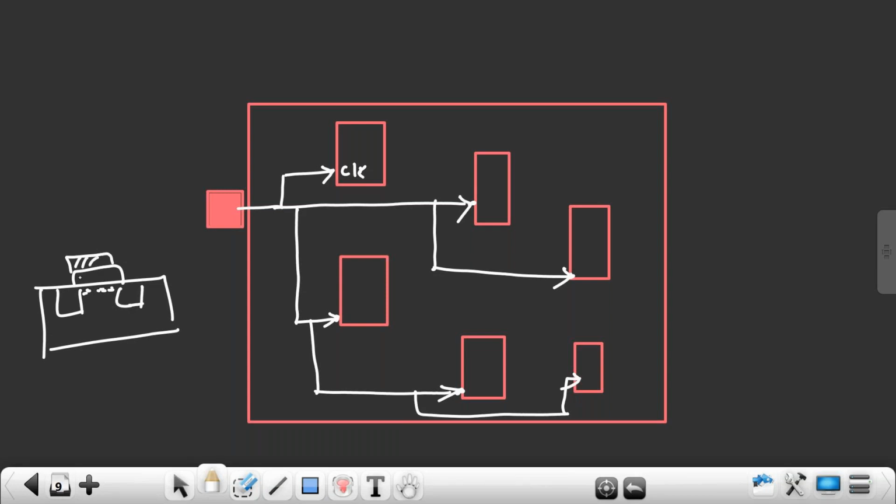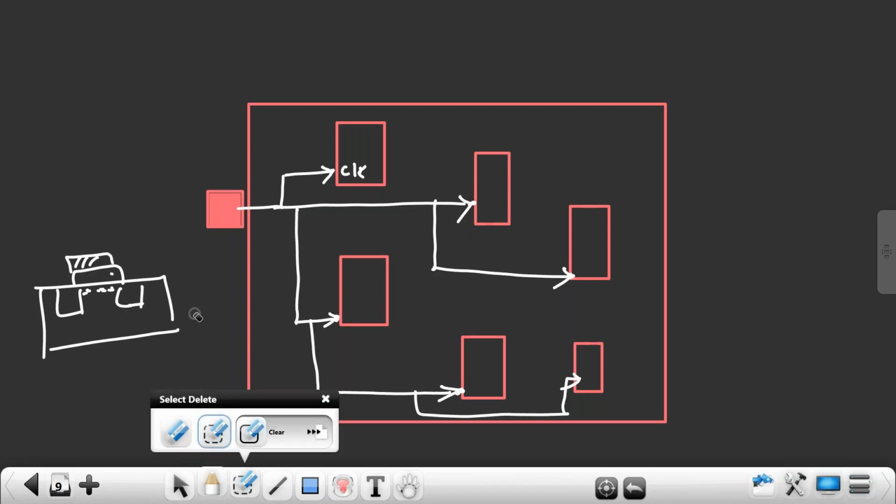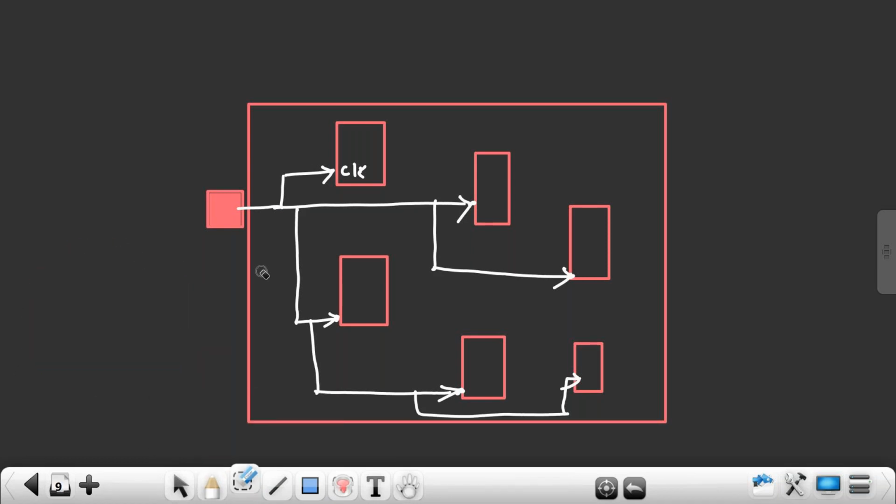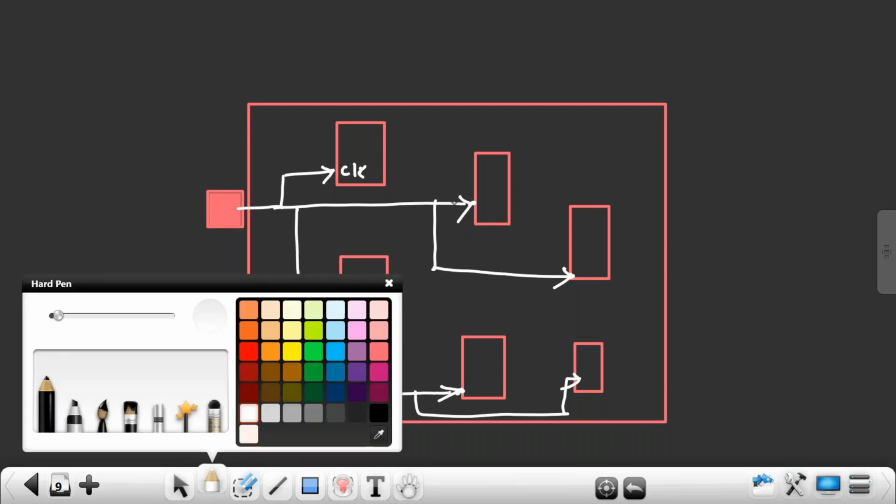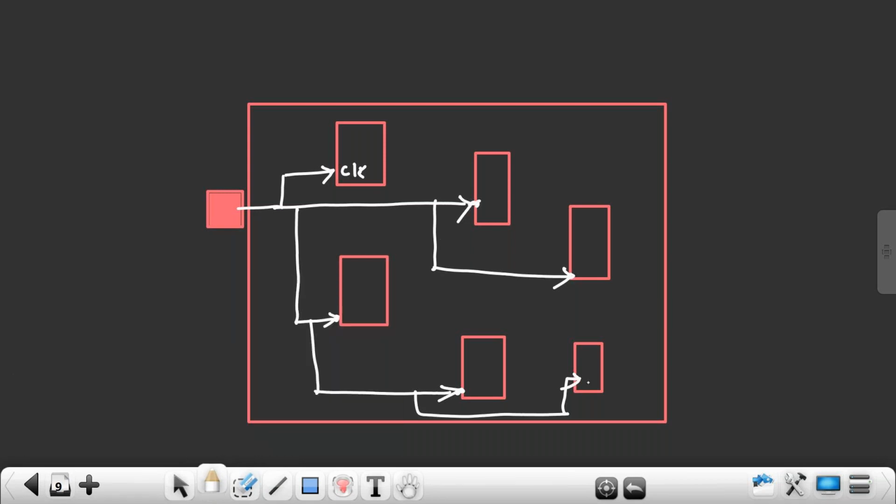So in between you have silicon dioxide, and below it you have electrons or negatively charged carriers. This forms one parallel plate capacitor. This capacitance is called pin capacitance. So every flip-flop has pin capacitance. The sum of all these pin capacitances will form the load capacitance to this port. This capacitance I am not connecting. It is forming because of the nature of these layers.